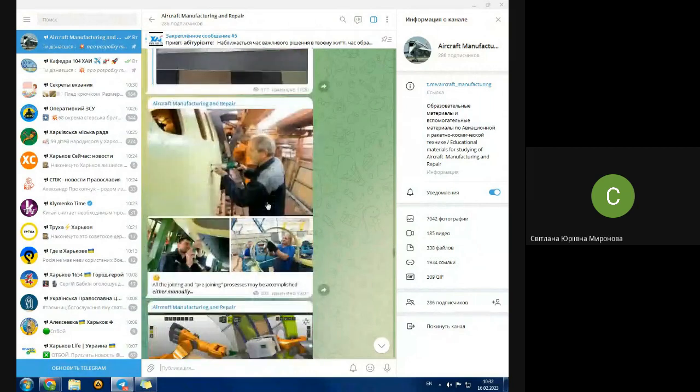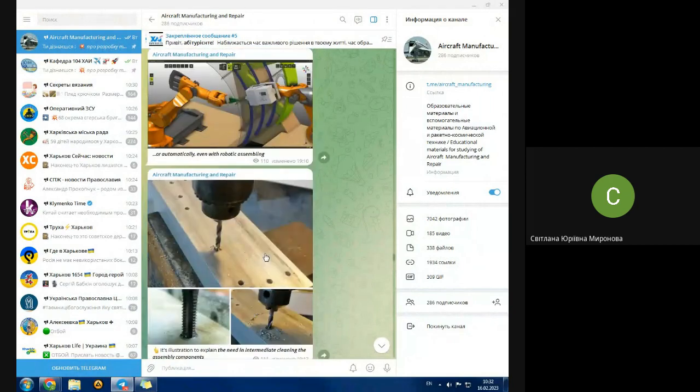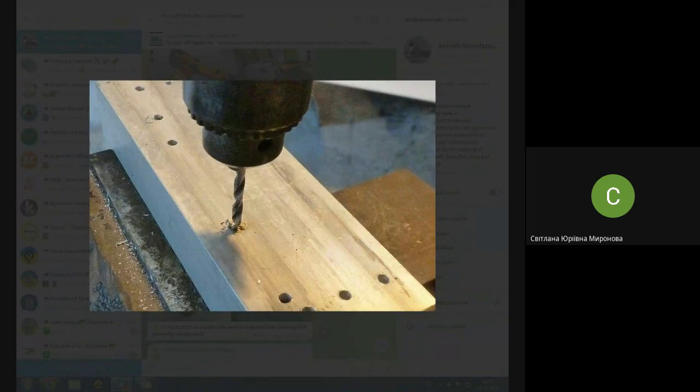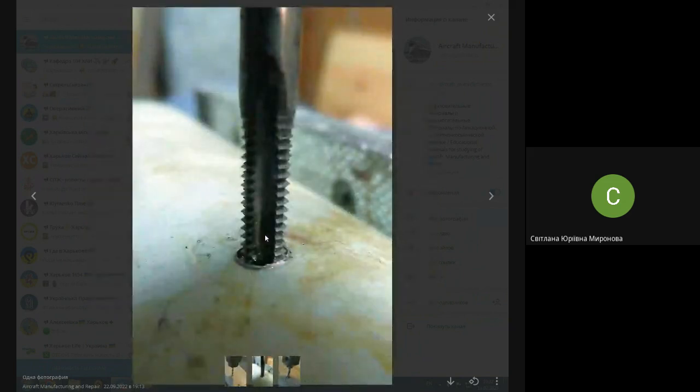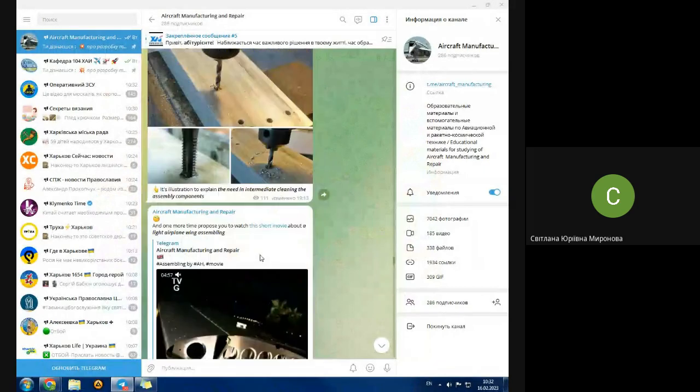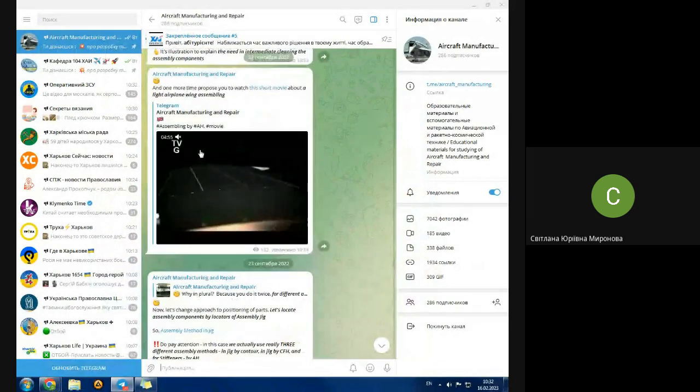That is drilling together, that is robotic assembling. Pay attention beforehand, before I even try to explain it. While drilling, we compulsorily have some portion of trash. They are called flashes, which stack up immediately on the hole, and dust and chips. When you drill some parts together, it may appear even between parts, in a stack of parts. Just keep it in mind for now. In this video, I'm not going to show it now.